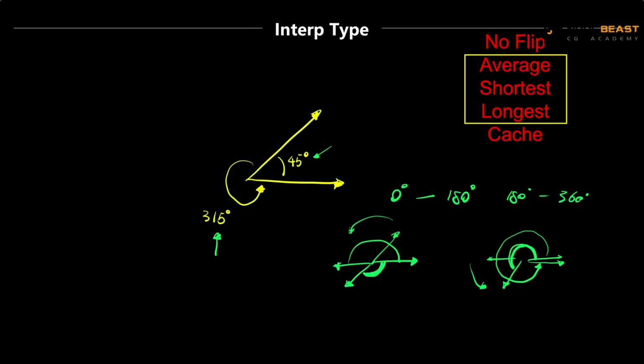At first glance, this method sounds smarter, like it might give a better result. But there's a problem here. We just mentioned it has to cache the previous frame every single time. So just think, if our scene has a lot of constraint nodes, this caching step will make our rig very slow, because the calculation load increases. Also, because it compares with the previous frame, we only get a previous frame when we are playing an animation. But rigging itself doesn't produce animation. This logic is actually more geared towards simulation, like when we do cloud simulation or particle simulation. It's not really related to rigging itself. So we don't really use these two. We can ignore these as well.